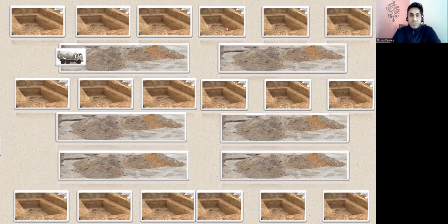Again, here it will be a problem for you to place the concrete. In the same way, here also, if you bring in the RMC truck, that is a transit mixer, it can place the concrete here, it can place the concrete here, but again it cannot go here because you already stored the soil. So you have done the excavation what you were supposed to do, but you did not plan it properly, because when the transit mixer came, it was very difficult for the transit mixer to make a movement. So you didn't plan it properly.